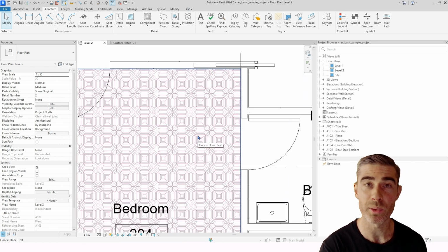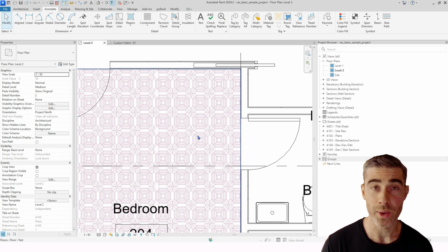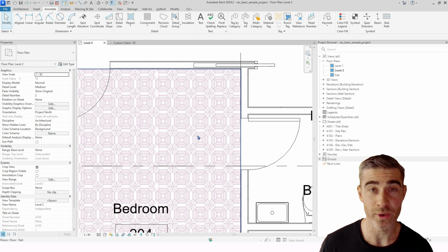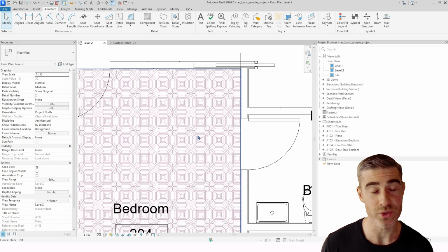It was as simple as creating those lines, creating that pattern using those lines, and at that point, using the pyRevit tool, grabbing those lines and creating a pattern for it. So in this way, there's no restrictions on the limits that you can go to designing these patterns for your floors and being able to replicate them in your working drawings.